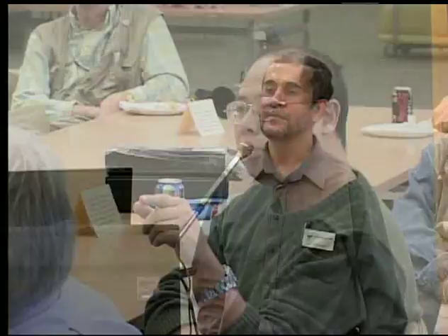Does that imply that if you increase the fan speed, H will increase as well? Yes, but to a limit. It's not exponential. It won't affect the distribution of temperature. So it's related between H and the difference of temperature, right? H depends on many parameters. It depends on the shape of the body, on the fluid we are using, and on the speed of the fluid. Also, if we have turbulent flow, H will be higher than for laminar flow, and so on.